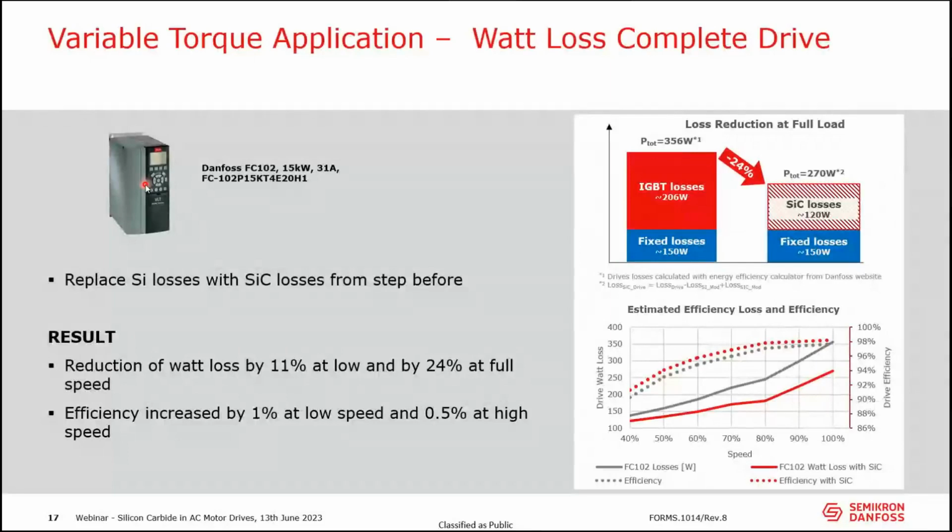There's a calculator that is related to the ERP regulation, so manufacturers have to push that out. I used that to calculate the drive losses in my load points, and then I subtracted the IGBT losses and put the silicon carbide losses on again. So the step that I did before is now applied to a drive. And what comes out,